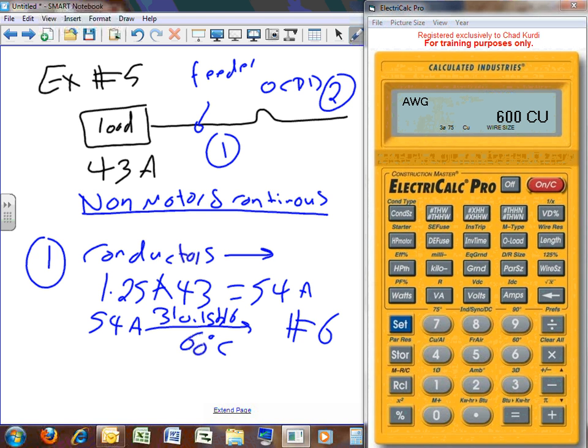Do you guys see how right here I can put any number of conductors based on the system that I'm dealing with? Does it matter what the voltage is? For all practical reasons, here I can put any voltage equal to or less than 600 volts, any voltage system that you can imagine. So for the sake of doing it, since we're doing single phase, that will be 3 conductors with a neutral.